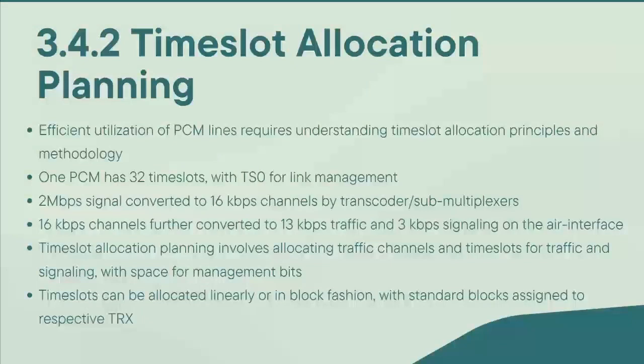So moving on to the next slide, which is about the time slot allocation planning. Efficient utilization of PCM connections requires understanding time slot allocation principle and methodology. As you may recall from our slide about the one PCM link, one PCM has 32 time slots with TS0 for link management, and a 2 megabit per second signal is then converted to 16 kilobit per second channel by the transcoder or submultiplexer.